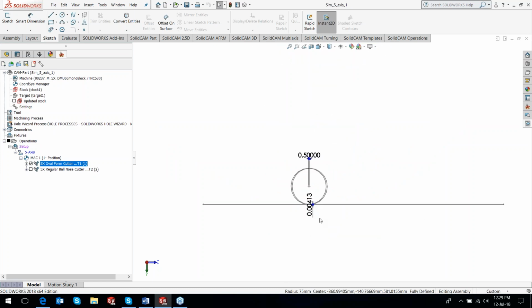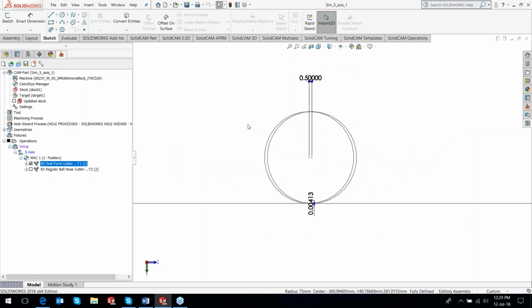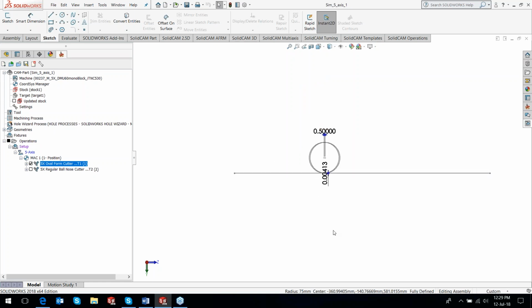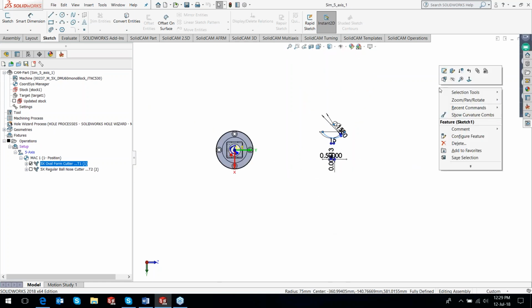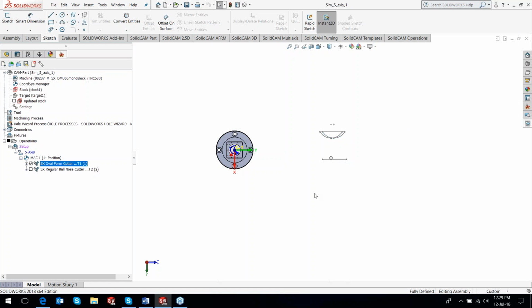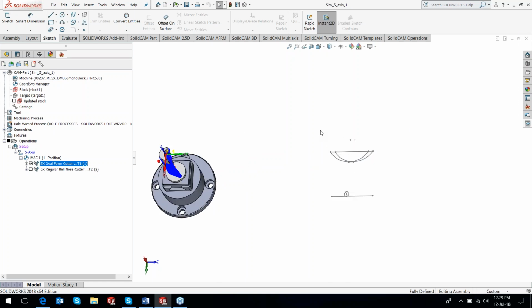And if I go to the 16 millimeter ball nose, to get the same scallop of 5 microns, I need a step over of 0.5. Okay, so this is basically how we estimate the side step for this particular part based on the scallop. So you'll get this part along with the sketch, and you can see how I've estimated the scallop.